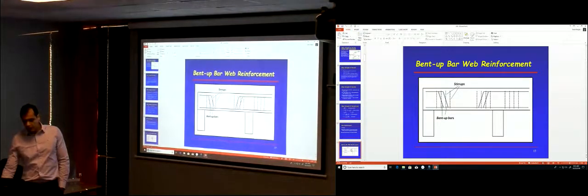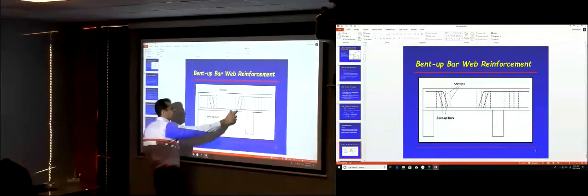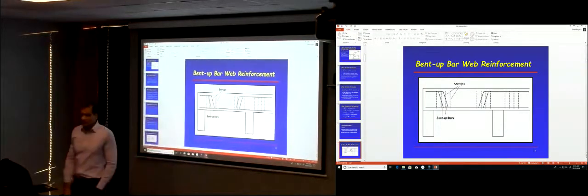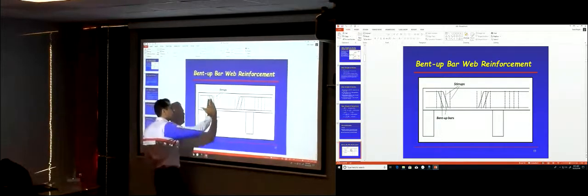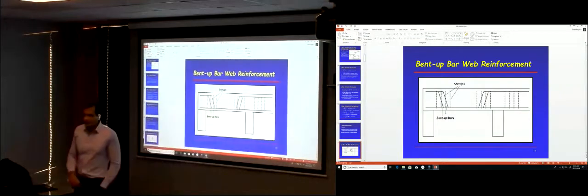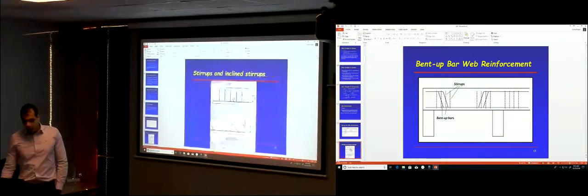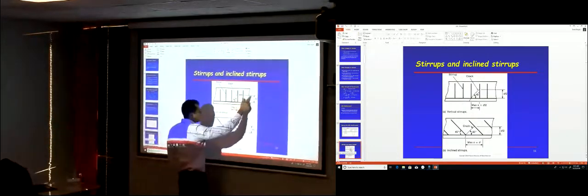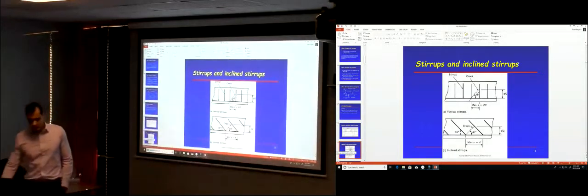So those are bent up bars here. You have bent up bars. You bend up the lower steel into top steel or negative steel. Okay, and while it's bent, it's over here. This bent up bar over here will resist some tensile force. Okay, or you can have vertical stirrups to resist the shear along that track, or inclined stirrups, okay, like to resist the shear.